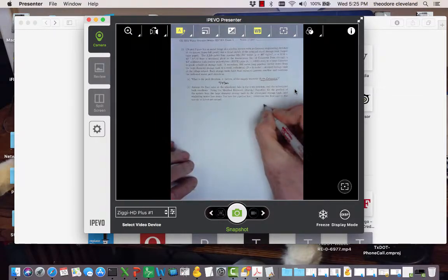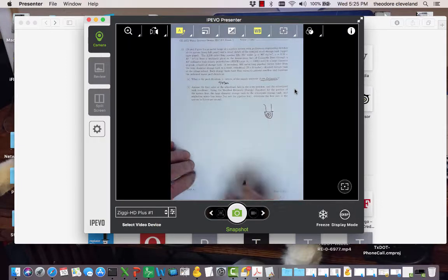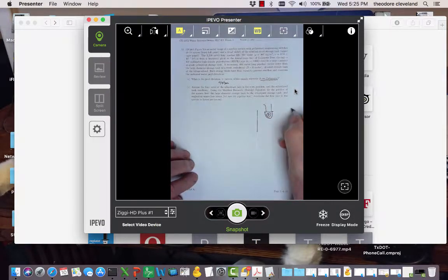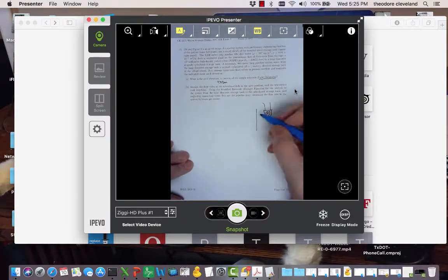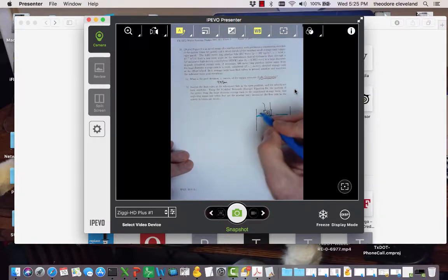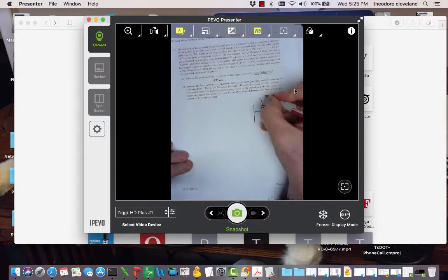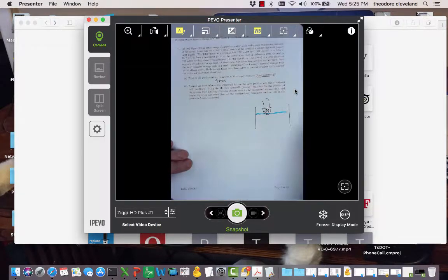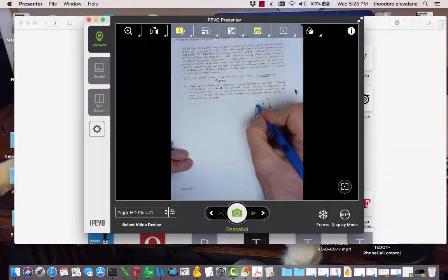So if we examine what the float valve might be like, there's probably a pipe coming down here. There'll be some kind of cage, and then there's a ball here that's supposed to be buoyant. As the water comes up, it's supposed to lift the ball and stop the flow, and somehow it becomes clogged so that our system has overflow.